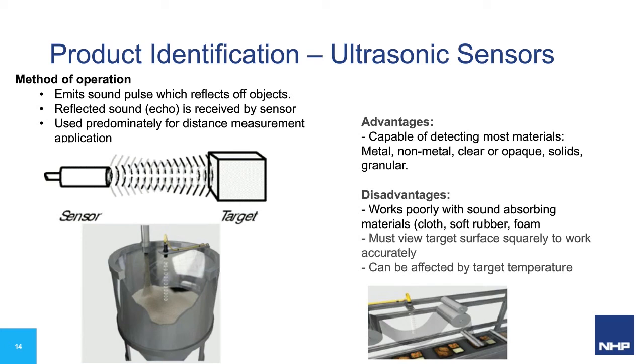And the disadvantages, however, are it doesn't work well if the sound is absorbed. It must also view the target surface head on to work accurately, so the sound waves reflect back. And they can be affected by hot surface temperatures as well.